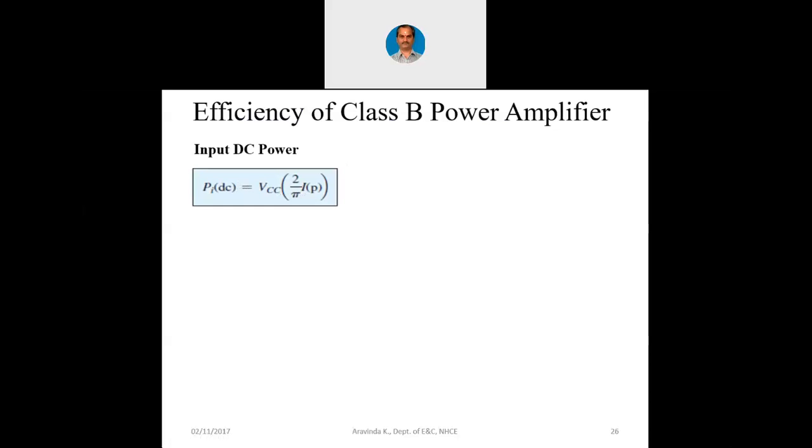So the DC equivalent of that AC is not actually the average, it is twice the value of peak voltage divided by pi. Now you know that the DC equivalent is slightly different from the RMS equivalent when it comes to waveform shapes. I will not get into all those electrical engineering basics, but this is now the input DC for class B.